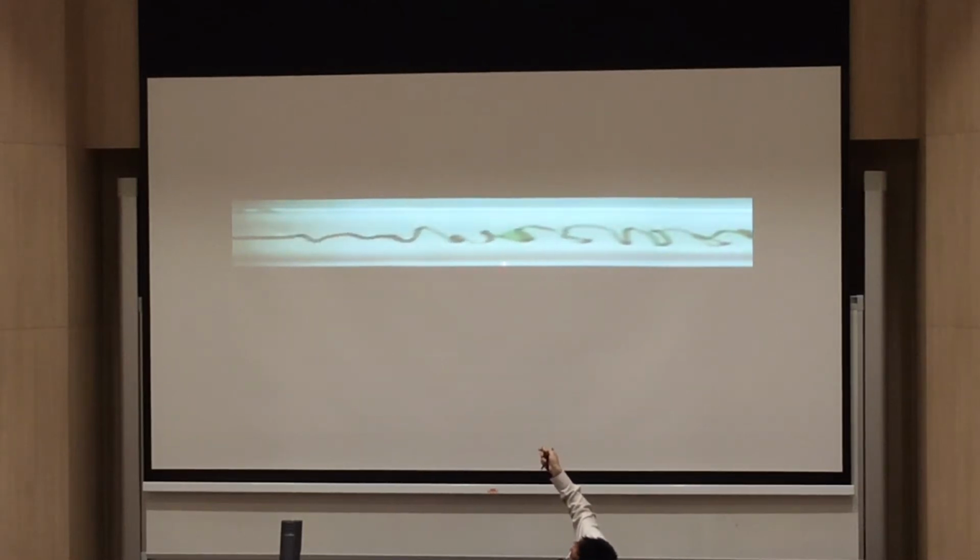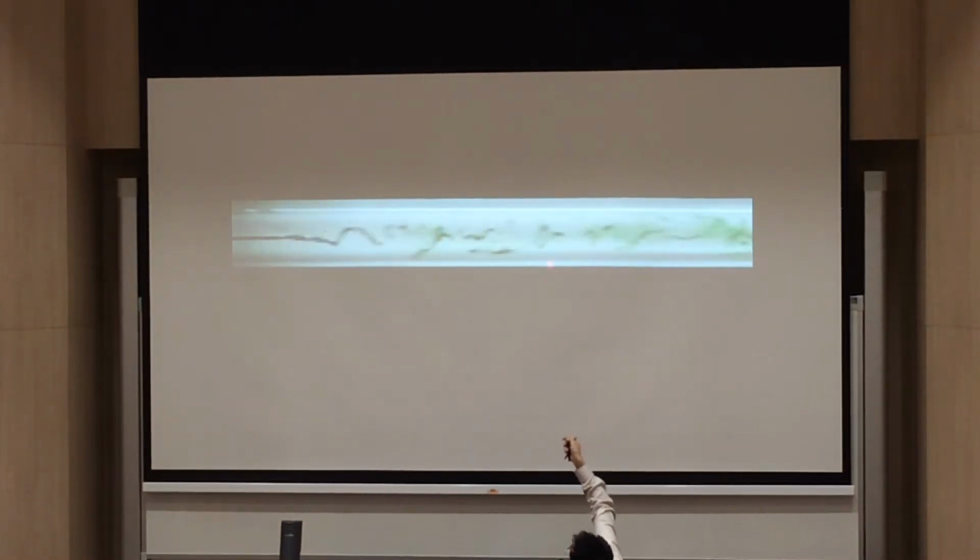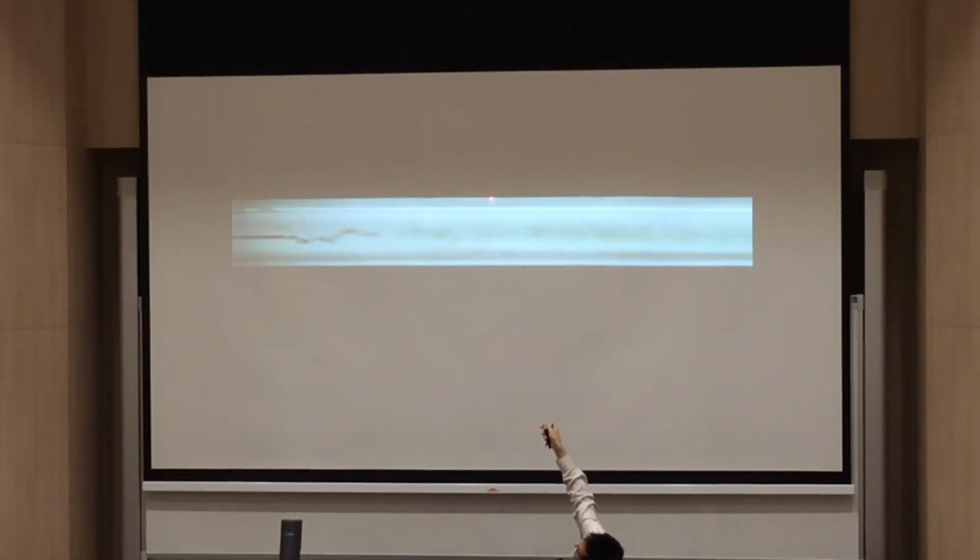So I want you to notice some part of time, the velocity over here, you can see that it's almost zero. You could almost see that velocity profile. This one. And then it increases the speed and you can't really see much. So at some instance, you could actually see that there is a certain velocity profile in that way. Because this is a pipe, the velocity that's nearest to the pipe wall will be almost zero, and the velocity that's right in the middle is where the highest velocity is.